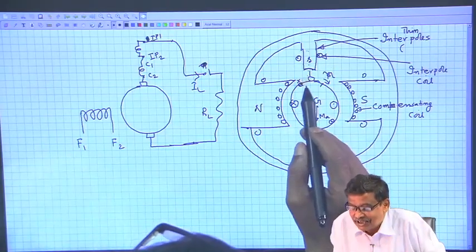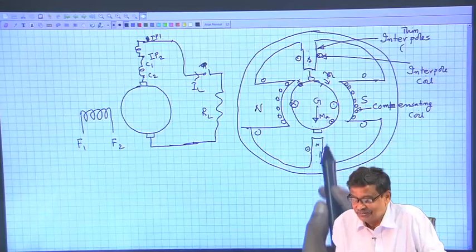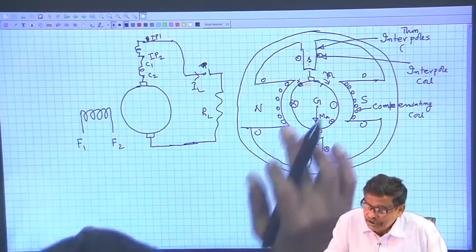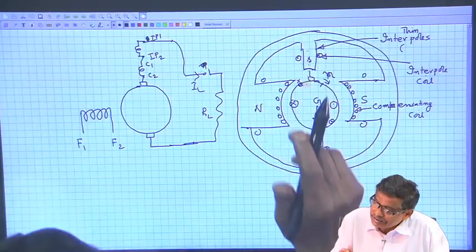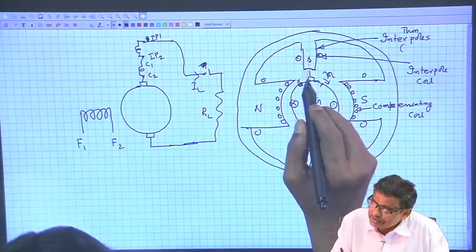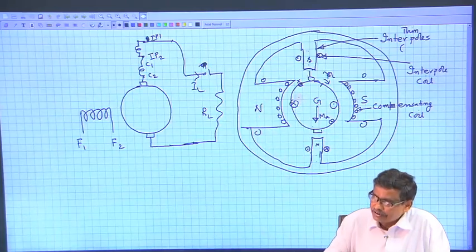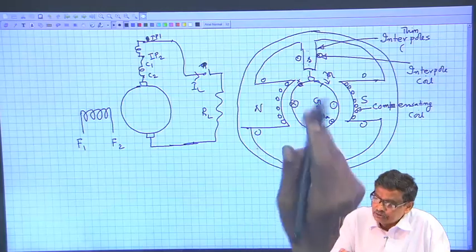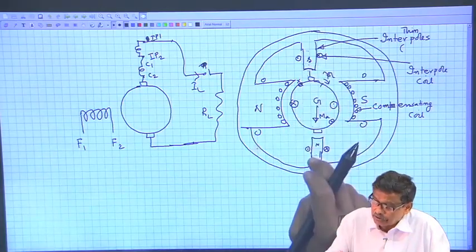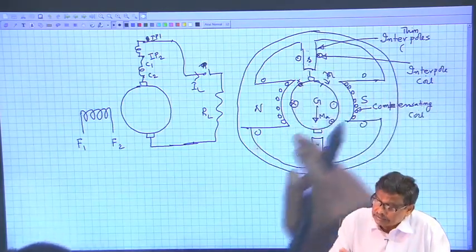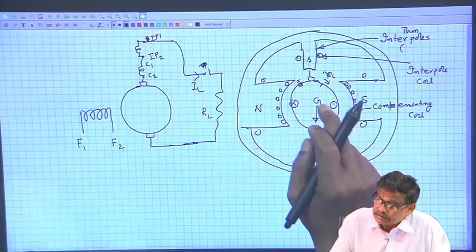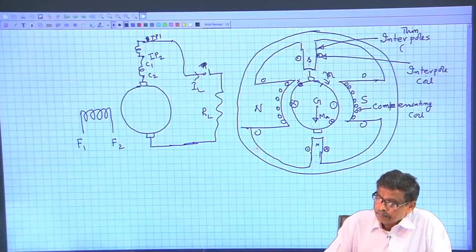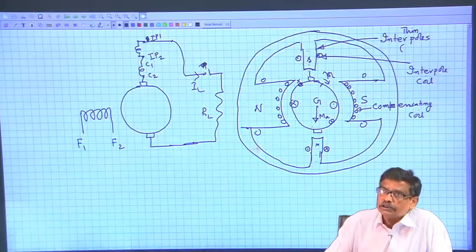Now, when it comes here in this zone, there will be induced voltage because of the armature reaction north pole that we have studied, and also because of the south pole. I can choose the strength of the south pole so as to nullify that armature north pole here; opposite poles I have brought in, and induced voltage will be 0.